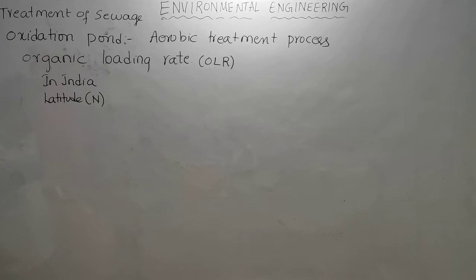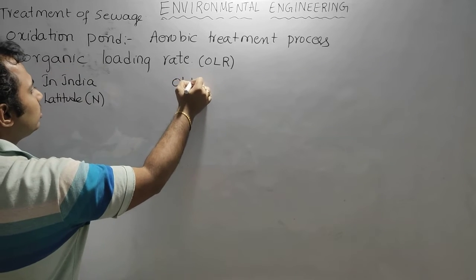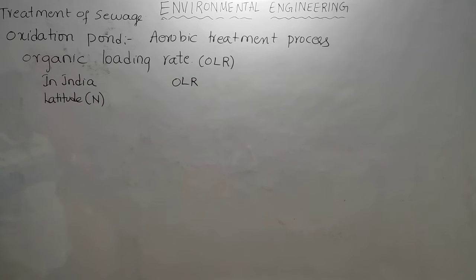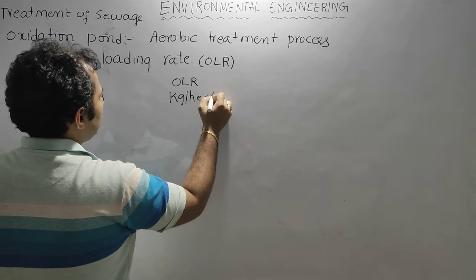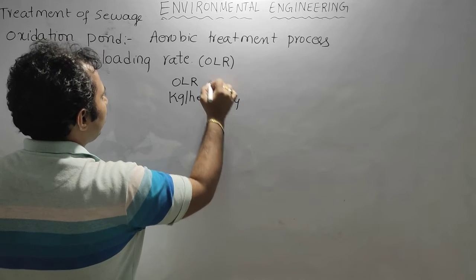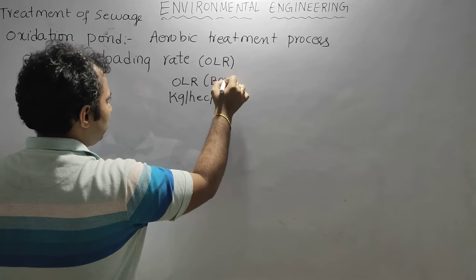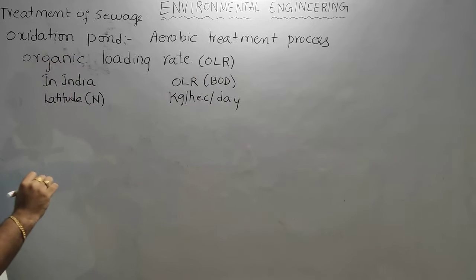Okay, latitude versus organic loading rate. The organic loading rate will be given as kg per hectare per day. Organic loading rate is nothing but BOD loading rate.